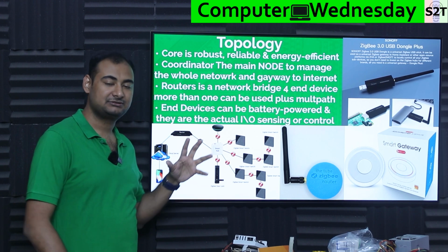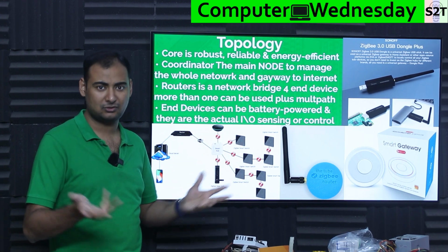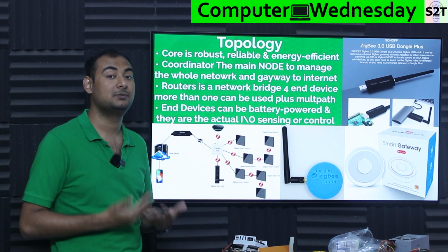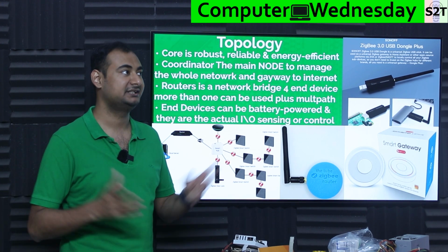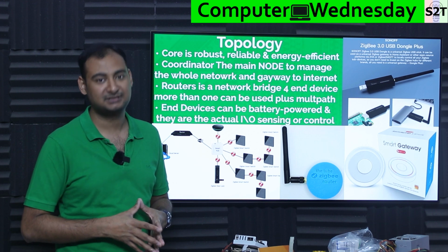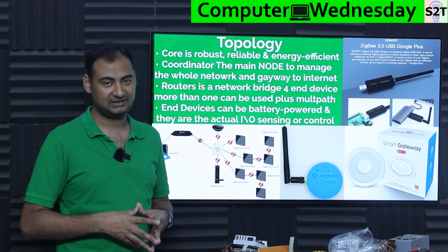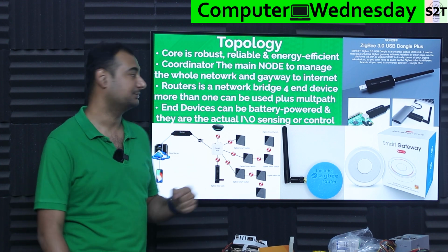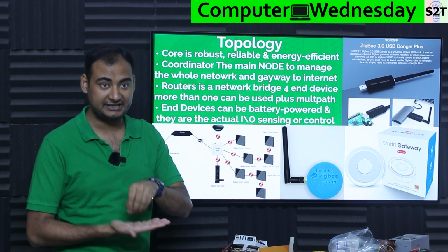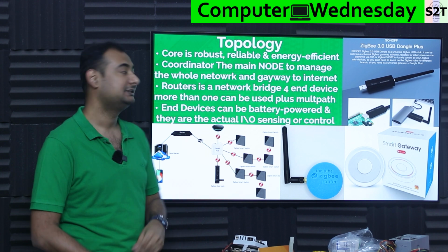Now be mindful, even though it was designed as a low-cost communication device, it was designed from day one to be robust, because they were expecting to put these in electromagnetically noisy environments. If you have ever worked around a plasma cutter, that destroys wireless signal. So you have to design in such a way that you can handle that. Robustness has to be built at the radio protocol level. It was done that way.